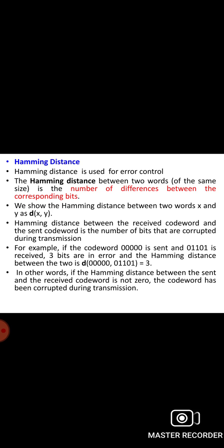For example, if you assume a data word for code word correction, comparing the received code word with the first code word, the receiver decides the first code word is not the one that was sent because there are 2 different bits. One of the central concepts in coding is Hamming distance.